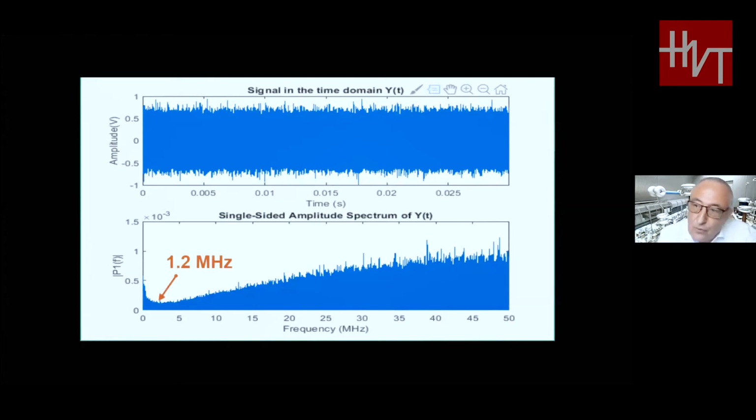Of course, when you use filtering, when you use the wavelet transform, you are also attenuating the signal. You are removing the noise, but attenuating the signal. It's clear. You have to pay a contribution to remove the noise, but you can distinguish pulses from noise, from exactly the noise that is modulated noise.